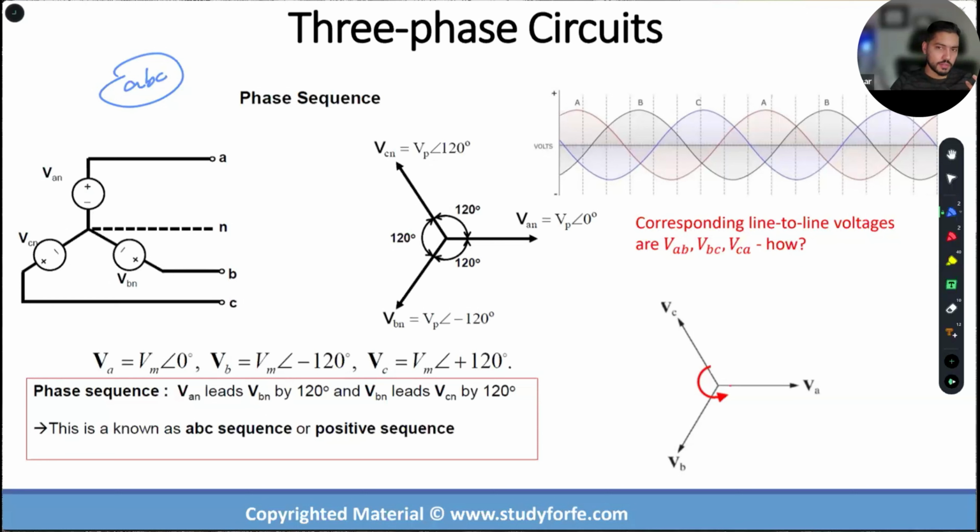So what is the phase sequence? That's the question. Phase sequence ABC, which in the context of sequence components or symmetrical components is also known as a positive sequence, although there is fine distinction between the two. ABC basically means that your phase A voltage is going to peak first, followed by B, followed by C. So if you literally hook up alligator clamps, okay, oscilloscope on the three phases, this is basically what you're going to see.